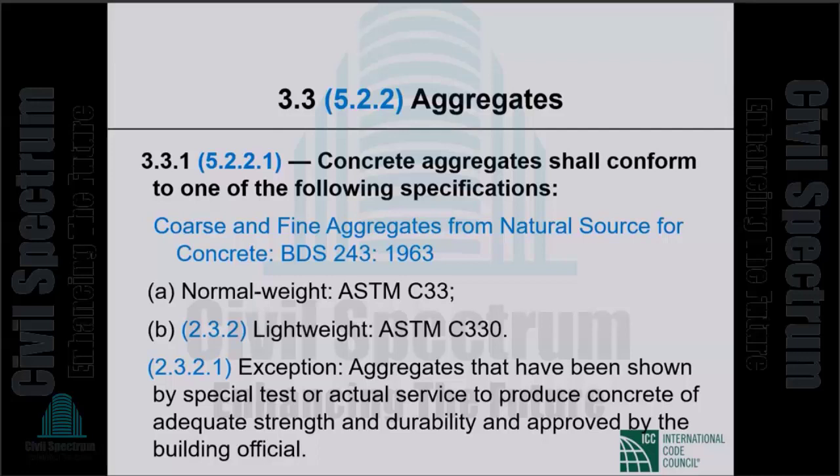Or in other words, you may use lightweight aggregate that is not in compliance with C330 if, as the exception says, it has been shown by special test or actual service to produce concrete of adequate strength and durability, the aggregate that you want to use, and it has been approved by the building official.